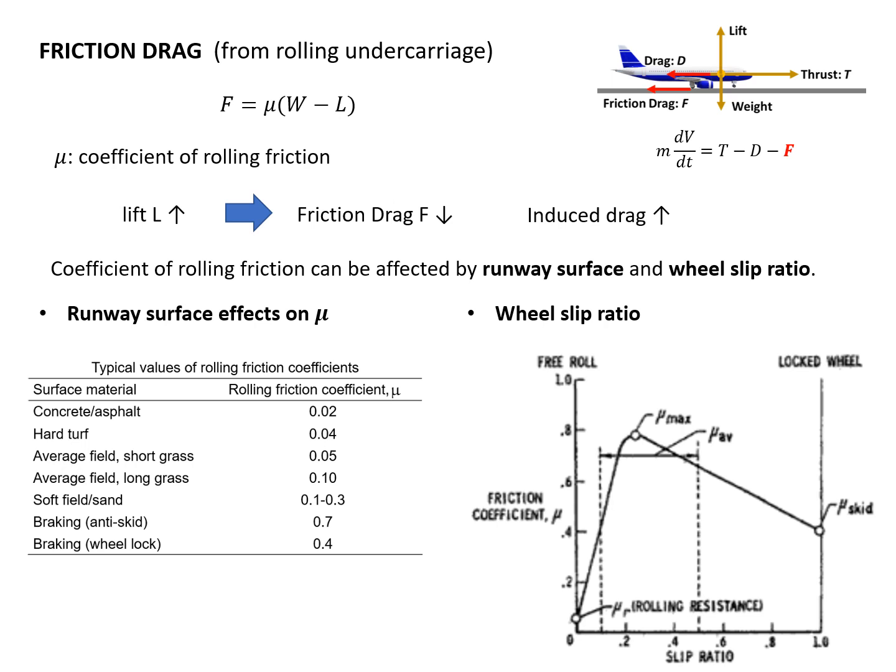at a slip ratio of about 0.2 something, let's say 0.25, and then decreases linearly to when the wheel is fully locked. So we can see the largest friction coefficient happens there.